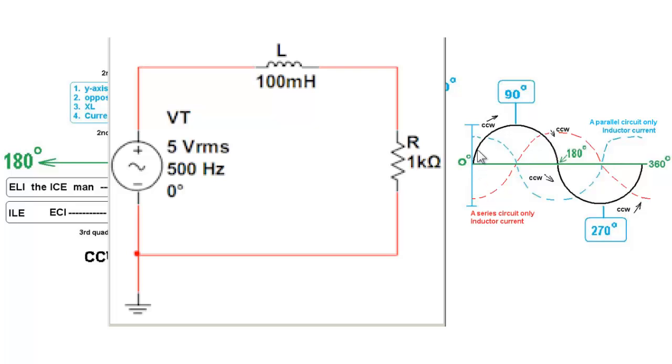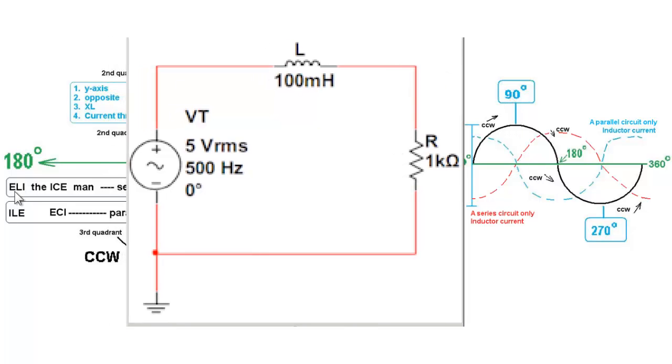And 90 degrees later, which is in a blink of an eye, in a few microseconds, the current through the inductor starts building up because it lags by 90 degrees. According to the mnemonic, voltage leads the current, or the current lags the voltage. The current is at a 90-degree deficit when the voltage is starting out. So the voltage is leading the current in this kind of circuit,